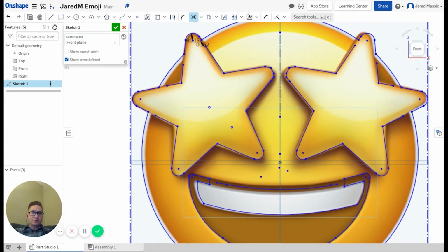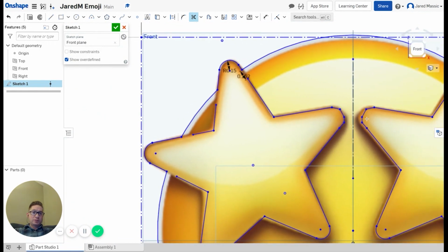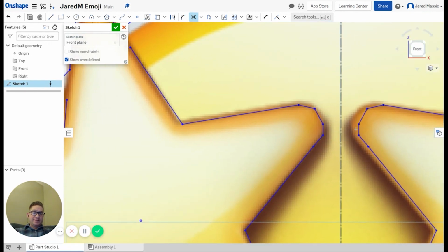We have the dimensions, at least, and you would want to check every cut line. So even between these two stars right here, as I cut through here and I cut through here, if the points between the closest ones, probably here and here, were closer than 0.15, I would be surprised if they didn't connect when you cut through one side and then cut through the other, right?